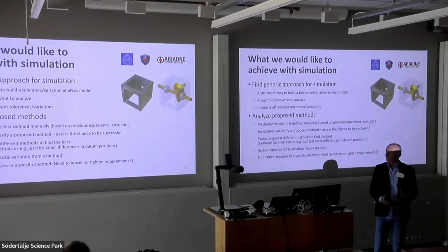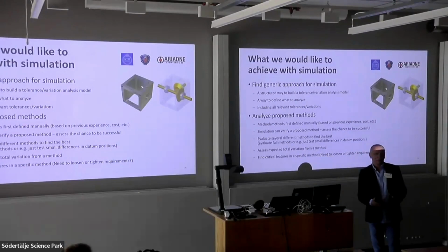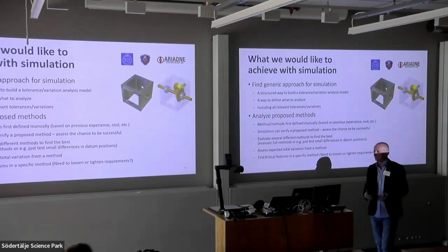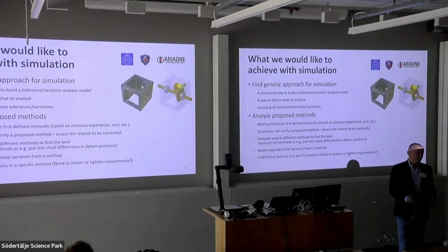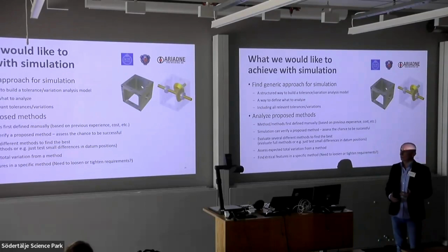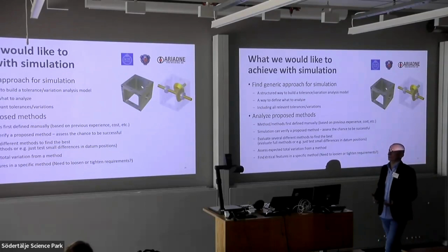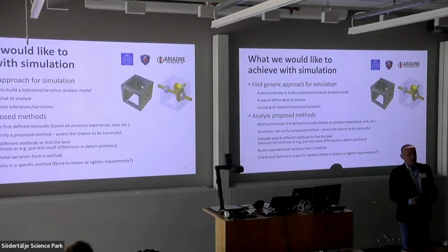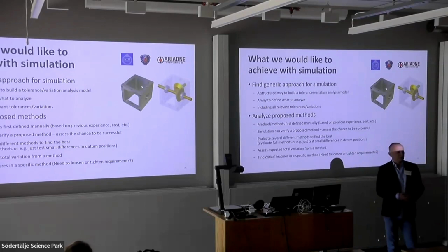If we have several ideas, of course, we want to compare them and find the best one, with the best quality and most cost effective. We want to identify all contributors and find out critical features and decide if we are good enough or if we have to tighten some tolerances or if we are able to release some of them.